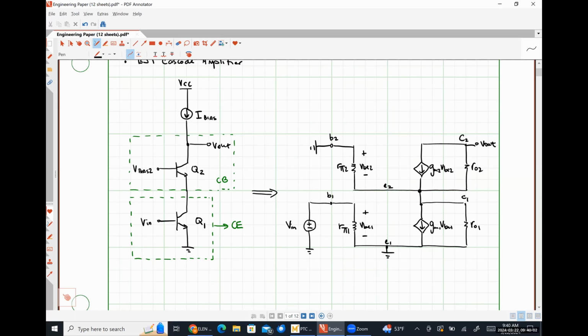Here's my output voltage. And then because I'm choosing to represent this as current source bias, everything beyond that is just an open circuit. So that's going to allow us to figure out how just this part of things works. And then later on, we'll see what happens when we connect transistor current sources up above, where realistically, that's just going to look like some finite resistance.